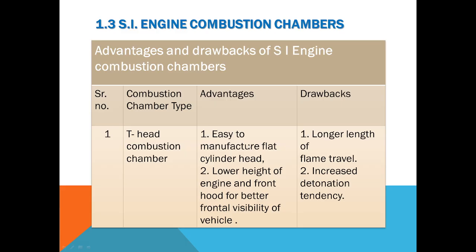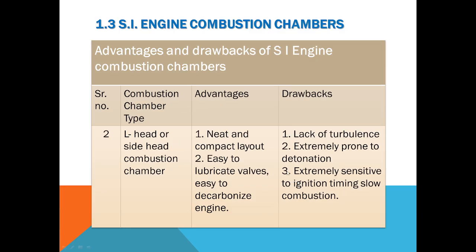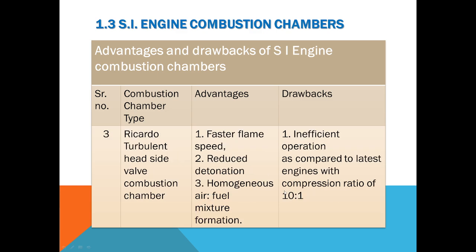T-head combustion chamber: it is easy to manufacture the flat cylinder head, with lower height of engine and a lower front hood for better frontal visibility of the vehicle. Drawback: longer length of flame travel, increased detonation tendency. L-head: neat and compact layout, easy to lubricate valves, easy to decarbonize the engine. Drawback: lack of turbulence, extremely prone to detonation, extremely sensitive to ignition timing, slow combustion.